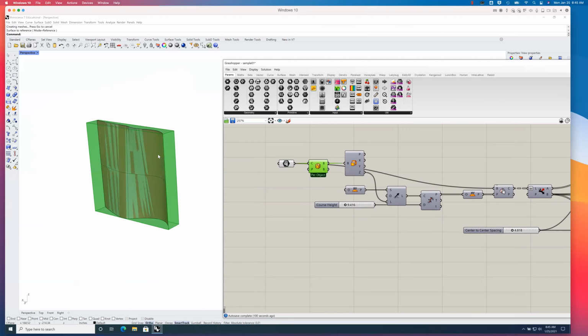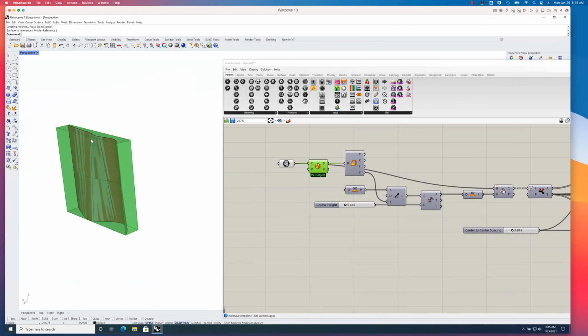First, what I do is I find the bounding box, the minimum size box that contains the entire geometry, right? There's a widget here that finds the bounding box for any piece of geometry. So I plug my surface into the geometry to contain, and it finds this minimum box to contain that geometry. The reason I'm doing that is because I want to see how tall this thing is. I want to understand where it is vertically, right? And so I'm going to find its Z dimension.